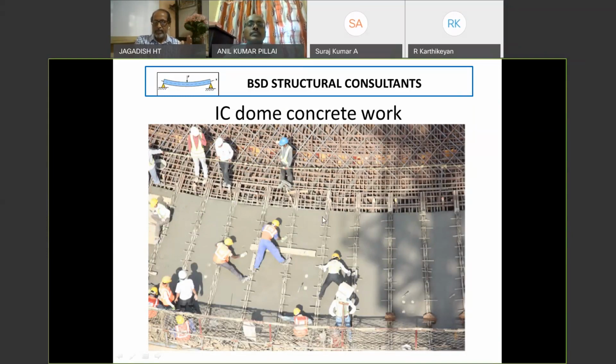Between the truss to truss, we install these wooden planks. That's the top formwork plank. The plank would be 25 mm, 32 mm thick. The width of plank would be around maybe 250 to 300 millimeters. Distance between truss to truss would be around a meter. So we go on putting the plank, 3 planks at a time.